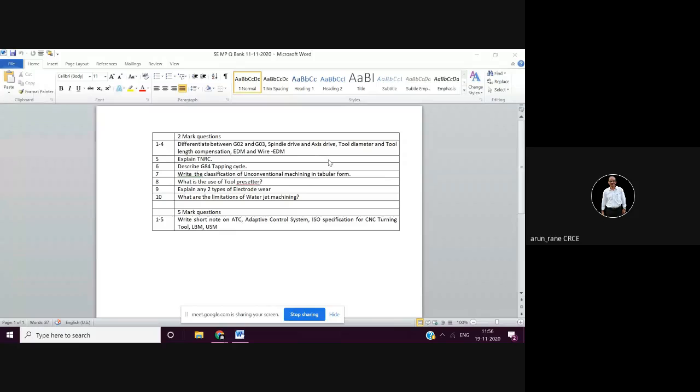Generally a 0.4 mm nose radius is used most commonly, 0.4 for finishing. Nobody uses 1.8 for roughing. Instead of that, a 0.8 radius is used for roughing. So 0.8 mm is used for roughing, 0.4 mm is used for finishing. Nobody uses 0.2 for finishing because it is too small, and nobody uses 1.8 millimeter for roughing because it is too big. Surface finish will be very rough.